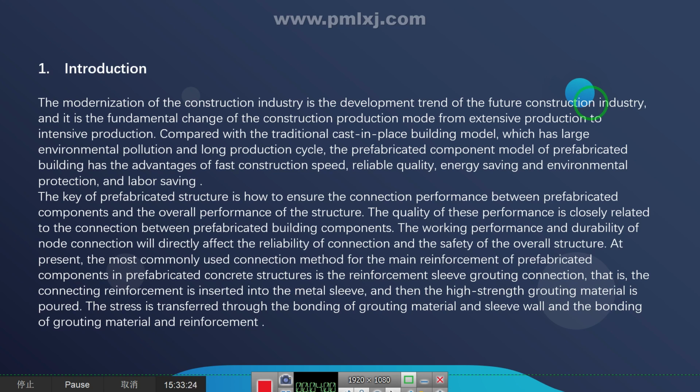The working performance and durability of the node connection will directly affect the reliability of connection and the safety of the overall structure. At present, the most commonly used connection method for the main reinforcement of prefabricated concrete structures is the reinforcement sleeve grouting connection.